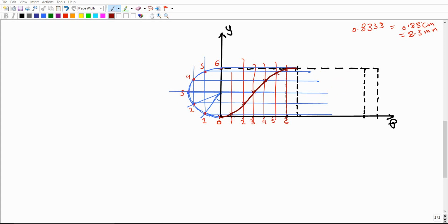Instead of redrawing another semicircle and breaking it down into 6 sectors, you can make use of this circle and use it for the other return period, as long as we have the same type of motion with the same specification, 150 and 50 lift, right? And this is what I'm gonna do. So again, this period should be 150 degrees.